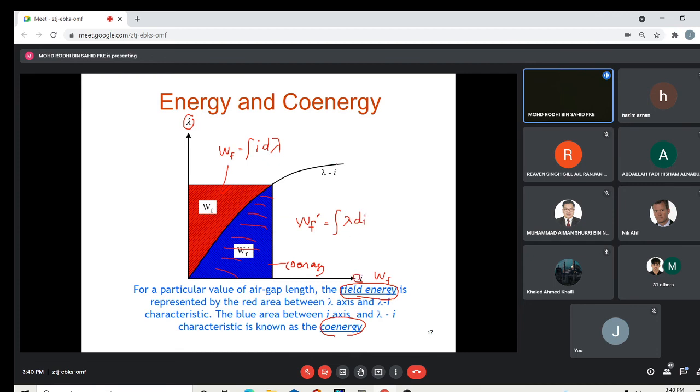Basically this equation is something like, if you still remember circuit theory, the step response. The voltage is equal to V final plus V initial minus V final times e to the minus t over tau. So basically it is an exponential term.